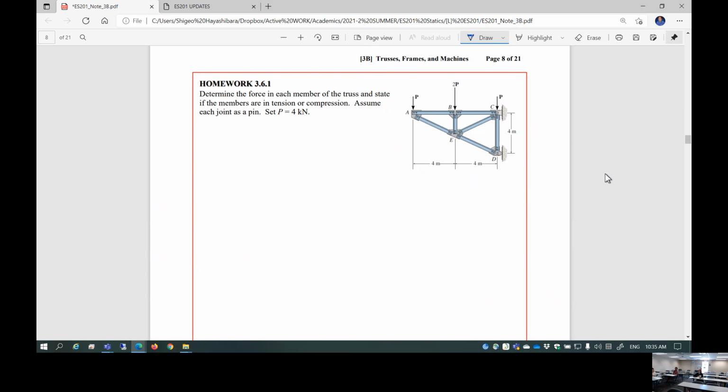Now, you understand that at each joint, you are not going to apply summation of the moment at that joint set equal to 0. That cannot be done. That cannot be done. Do you understand that? Because all the forces are acting into the joint, summation of all the moment at that joint is 0 equal to 0. There's no information you can squeeze out by applying moment summation at each joint, of course. You know that, do you?